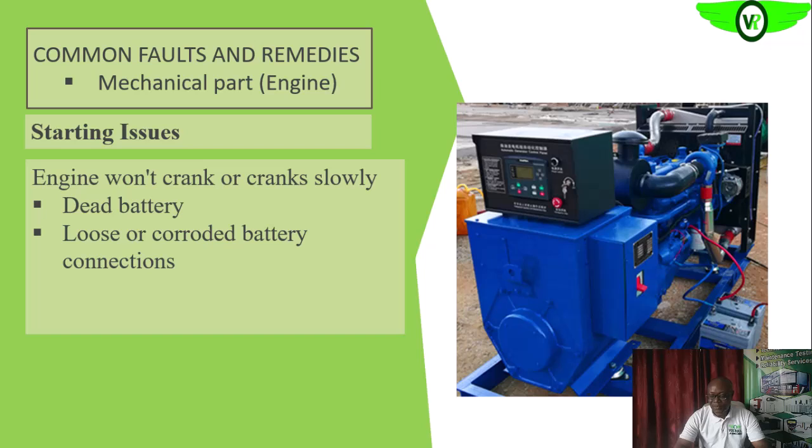Then if we have partial contact around the battery terminals, even around the battery terminals at the battery itself or the starting motor itself. Okay, so if we have partial contact in any of these terminals, of course it will cause the engine to crank, or the cranking will be too slow that it will not be enough to start up the engine.